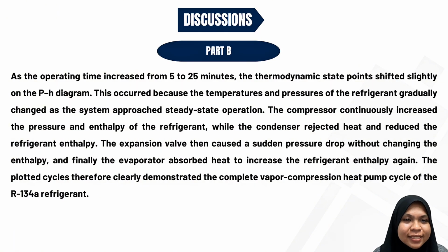The compressor continuously increased the pressure and enthalpy of the refrigerant, while the condenser rejected heat and reduced the refrigerant enthalpy. The expansion valve then caused a sudden pressure drop without changing the enthalpy, and finally the evaporator absorbed heat to increase the refrigerant enthalpy again. The plotted cycle therefore clearly demonstrates the complete vapor compression heat pump cycle of the R134A refrigerant.